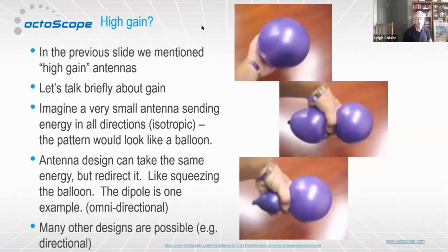But for example, if you wanted to use the test bed at a lower frequency, we do get requests for that from time to time, let's say 900 megahertz. You can see that the antenna that I showed would have quite a high return loss at 900 megahertz, but it's certainly possible to get 900 megahertz antennas and use them. So that is what you do. Return loss is really an antenna characteristic, and you use that in order to design your test.